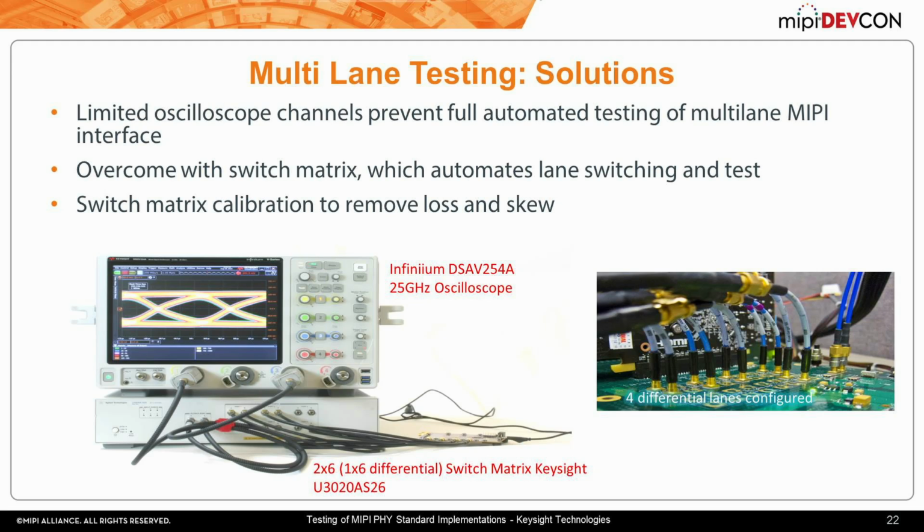There's also some other considerations when you think about this, and that is no matter how good this de-embedding or loss removal software is, you're fighting a losing battle when you make these connections very, very long. And that is because as you have more and more loss, the removal is essentially applying an inverse filter.